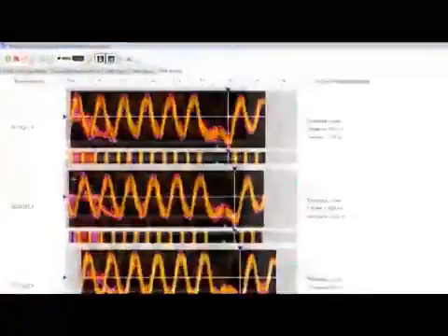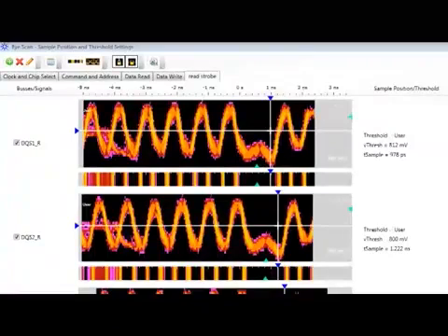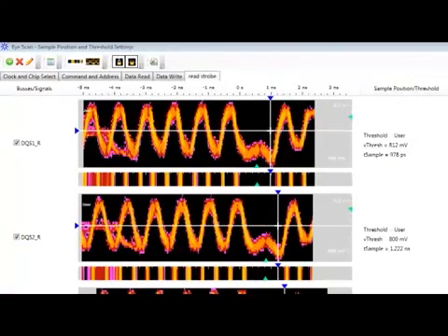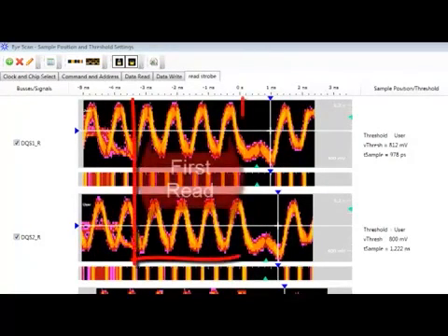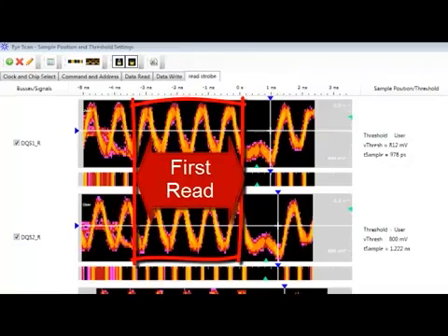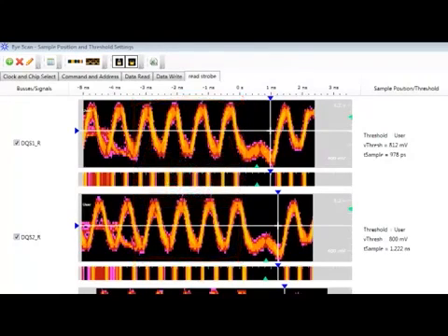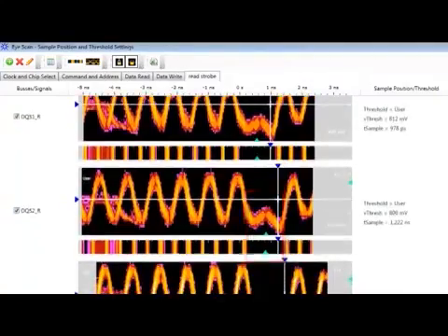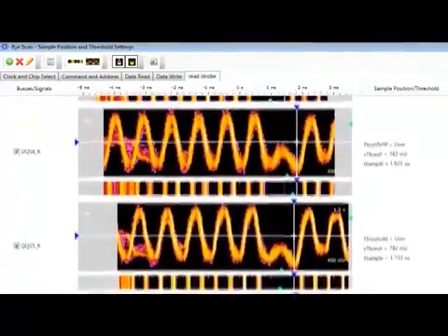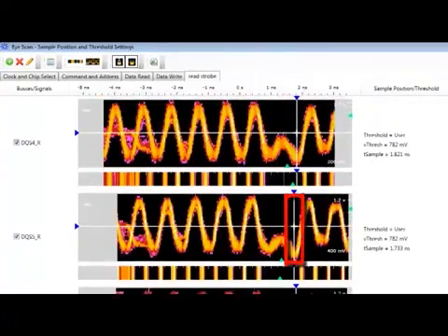We see on the left-hand side the first scan starting where it came either out of a back-to-back read or sometimes a preamble of tri-state into the read. We see all 8 samples of the first burst. Then we see the time where the no-op and the strobe was released. Some of the signals are floating up to the tri-state. On all signals, we see the time where the preamble before the second burst came in and began scanning.